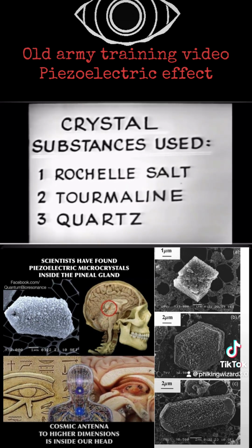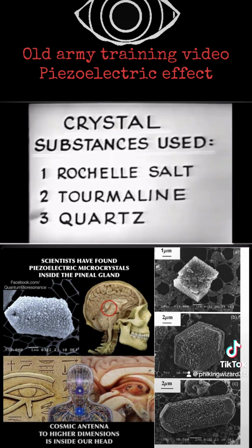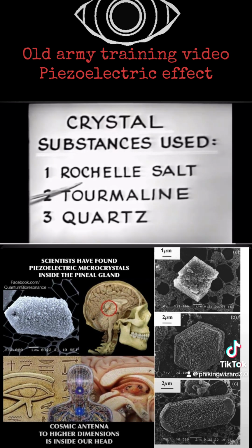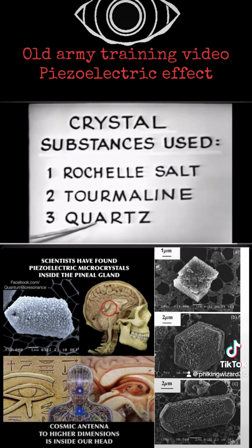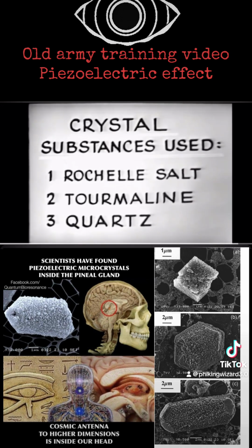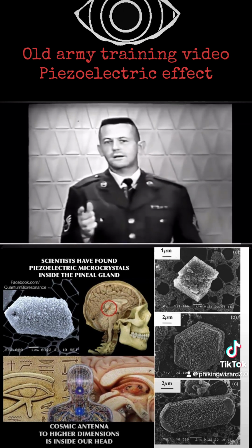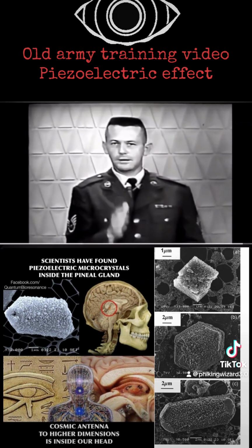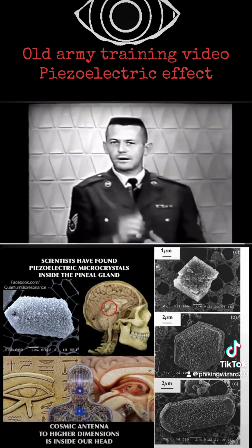Then we saw the three substances used: Rochelle salts, tourmaline, and quartz. We said that Rochelle salts exhibit the piezoelectric effect to the greatest degree, but that quartz is most generally used because of its mechanical strength. This represented the crystal holder, this the crystal itself. Now, in concluding, we can say that the one big advantage of the crystal is its frequency stability. Remember, it has a very high Q, giving us a very narrow bandwidth.